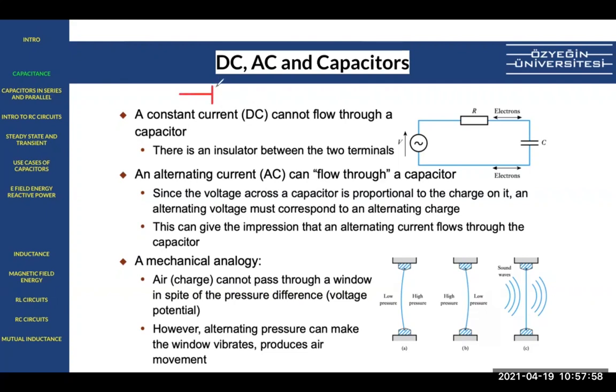What does it mean? So when we have a cap connected to two sides, this is, let's say, Vx, and let's say this is Vy. At DC, which means frequency of 0, yes, it is open, right? Because the cap is 1 over j omega C. In the Laplace domain, omega is 0, so this goes to infinity, right? So that means at frequency of 0, this cap acts like an infinite impedance. Infinite impedance means it's open. So if any voltage at this side at frequency of 0, we don't see it here.